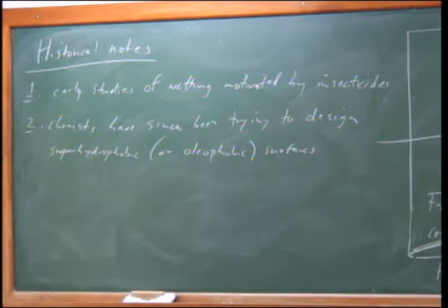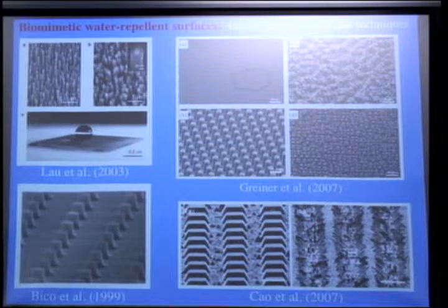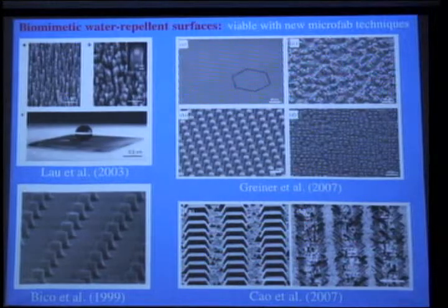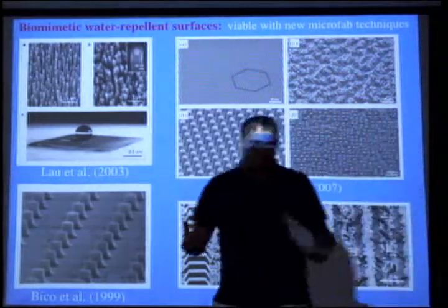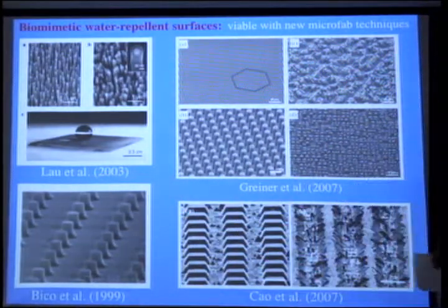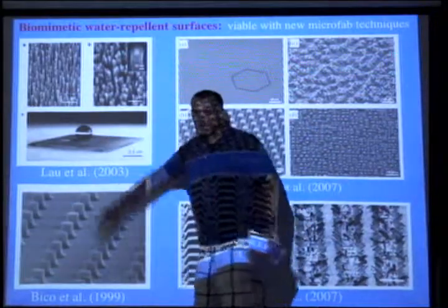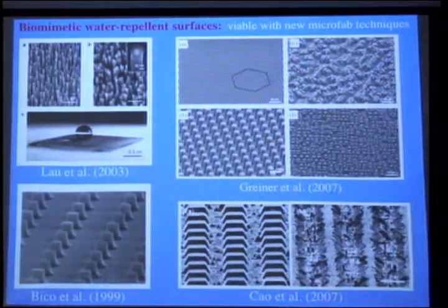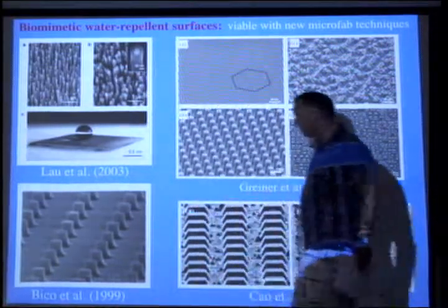Okay, and so these are some recently designed super hydrophobic surfaces, and actually one guy came. It's like one of the useful applications of fractals: somebody designed a fractal-like surface. So basically, again, there's going to be a huge energetic cost because there's a very large surface area if you have something incredibly rough. But these are some surfaces, and again, you can increase the contact angle enormously by making them very rough. So again, just increasing the energetic cost of wetting. And again, this is possible now. So we have some scale bars here. Yeah, so this is 50 microns. So you have texture down to about 50 microns.